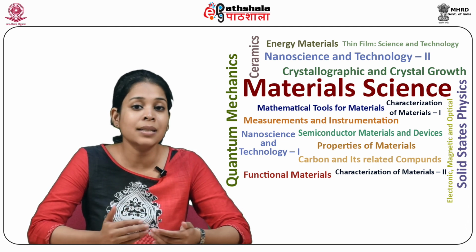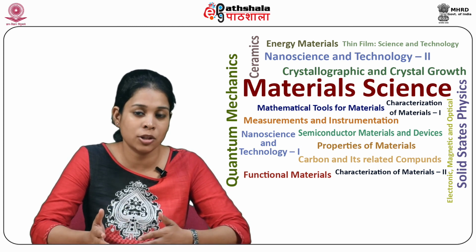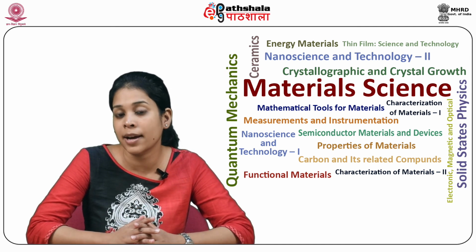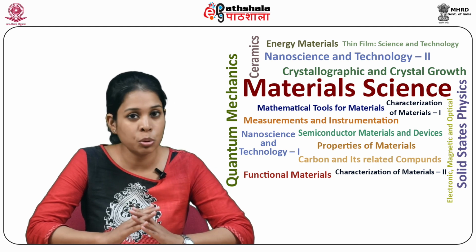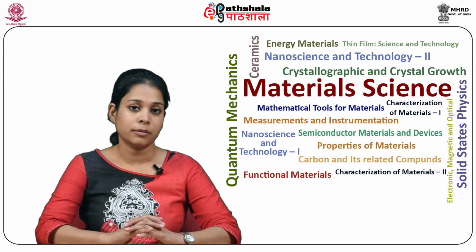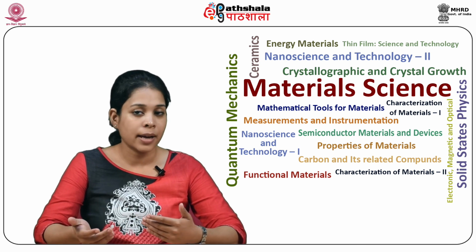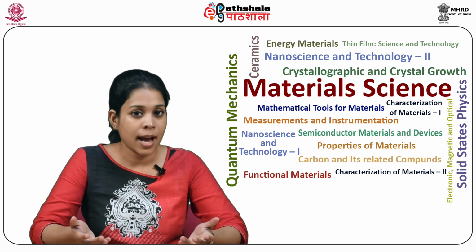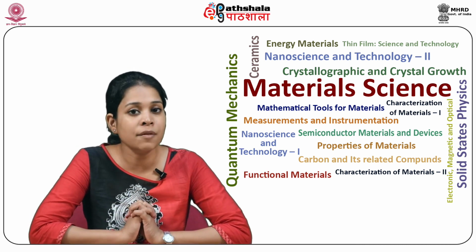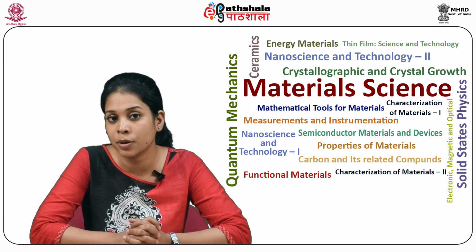The magnetic tapes are made of elongated, 0.2 to 5 micrometer long hard magnetic oxide particles of gamma ferrite, that is gamma Fe2O3, embedded in a non-magnetic binder. The particles are single domain, magnetized along their major axes, which are aligned in the plane of the tape. The coercive fields are typically between 50 to 100 kiloamperes per meter.